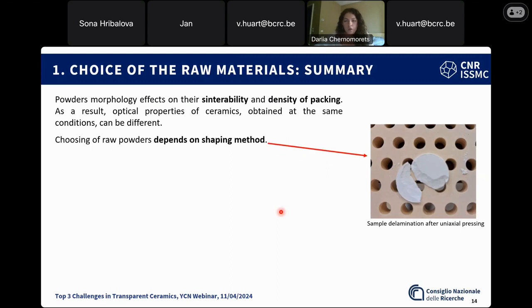Here we can see zirconia-doped yttria ceramics obtained by vacuum sintering before annealing, but after annealing it's colorless and transparent. So probably it can be one more step in producing ceramics using sintering aids. But of course, it depends on the material, type and amount of sintering aid and the sintering process, as well as advantages and disadvantages.